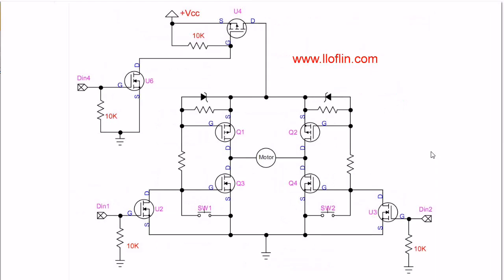All right, in this variation, I have replaced the ULN2003 with 3 separate N-channel small MOSFETs. In the case here, for instance, a high in will produce a low out on the drain. It will switch on U4 and supply power to the H-bridge.